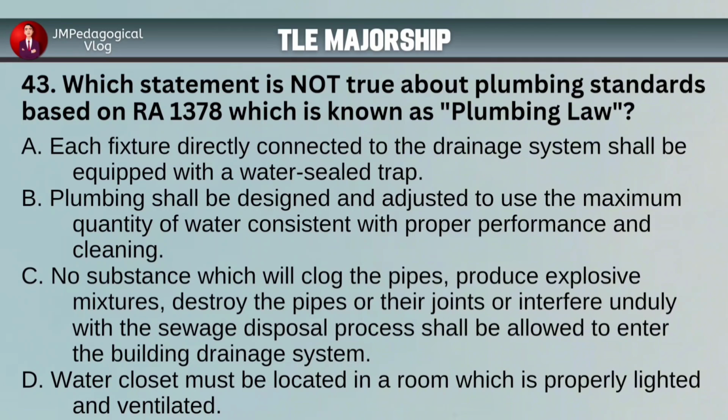43. Which statement is not true about plumbing standards based on Republic Act 1378, which is known as Plumbing Law? A. Each fixture directly connected to the drainage system shall be equipped with a water-sealed trap. B. Plumbing shall be designed and adjusted to use the maximum quantity of water consistent with proper performance and cleaning. C. No substance which will clog the pipes, produce explosive mixtures, destroy the pipes or their joints, or interfere unduly with the sewage disposal process shall be allowed to enter the building drainage system.